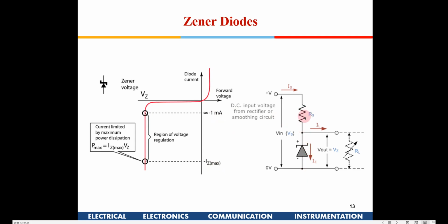So ideally you will take an RS value which is somewhere in between these two. Exactly in between. Why do we take it in between? Now when you connect a load resistance, if the load resistance changes also, it will continue to maintain this voltage. This voltage will be 6 volt irrespective of